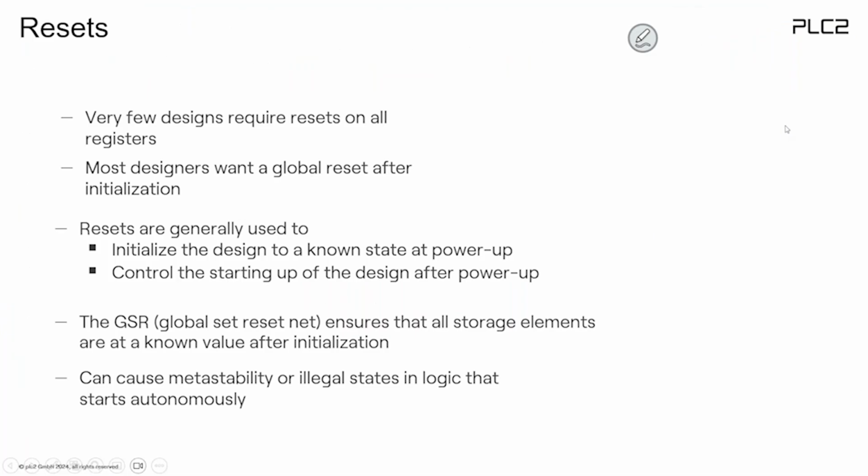So the reset. Just a few words about the reset. Actually, very few designs require reset on all registers. Very few. Resets are usually used to put the circuit in an initial state. That's actually what we need. And there's one element for us in the FPGA called the GSR. Whenever you switch on and configure your FPGA, you will get a global set reset, and all of the internal registers will be cleared.